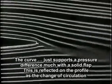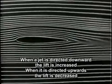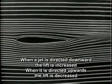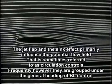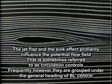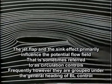This is reflected on the profile as a change in circulation. When the jet is directed downward, the lift is increased. When it's directed upwards, the lift is decreased. The jet flap and the sink effect primarily influence the potential flow field. They are sometimes referred to as circulation controls. Frequently, however, they are grouped under the general heading of boundary layer control.